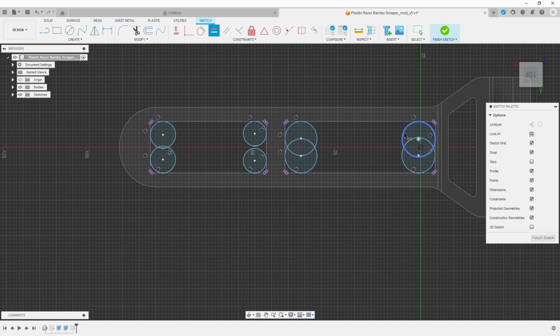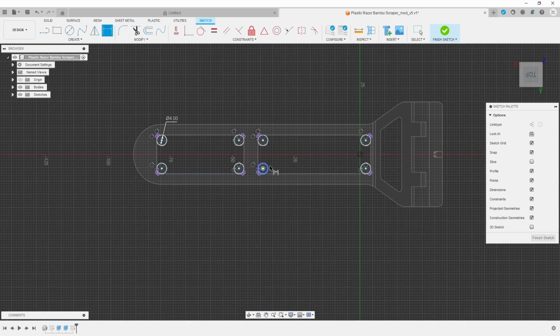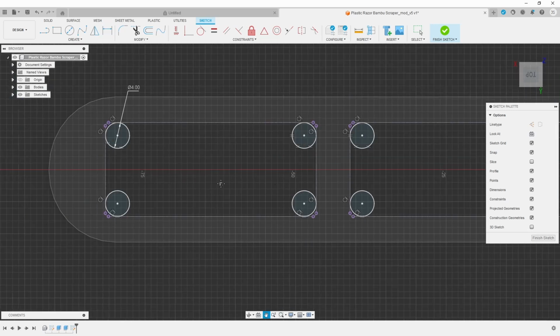So it's just a matter of going through and clicking 2 circles to set them equals to each other, selecting one group of circles and working through that. So then select a radius, try 4, looks a little smaller than what I want, so I'll go up to 6.